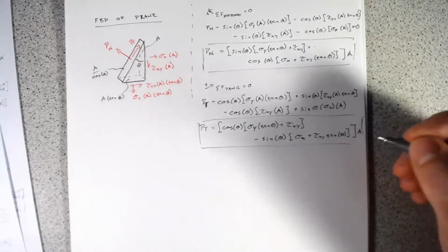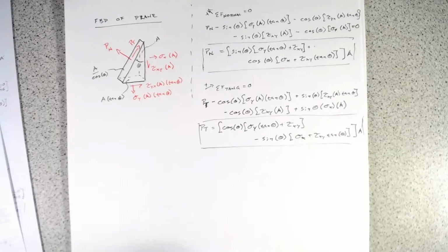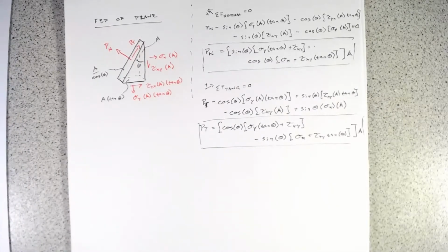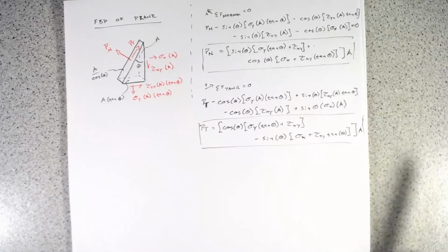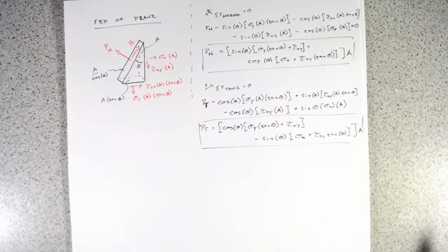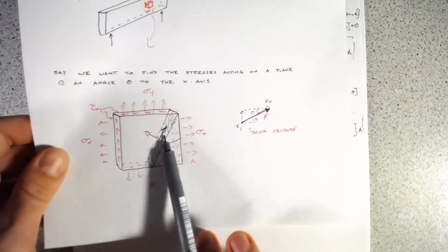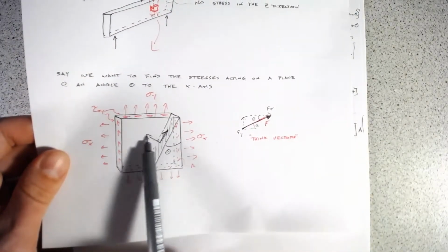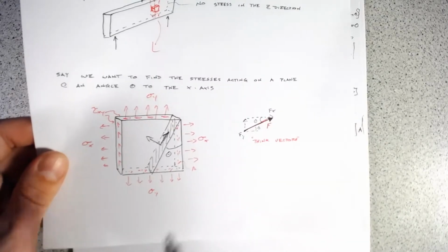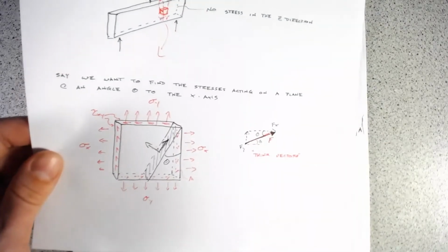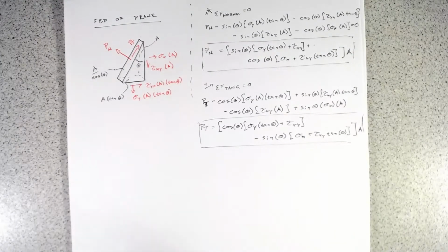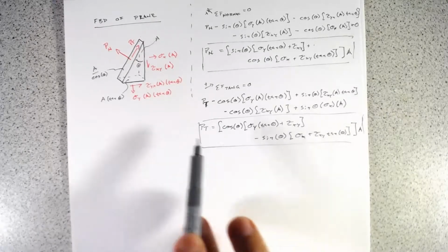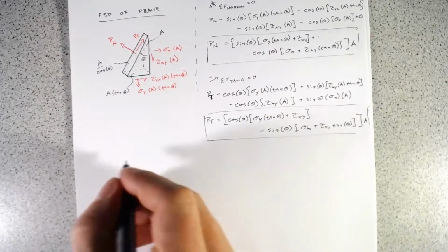forces. And again, and I'll do this throughout the lecture, just try to remind you of what our whole goal is. So the forces is well and good, and that's a lot of trigonometric functions. But remember, what we're looking for are what these stresses are going to be at this inclined angle, because we're looking for what these maximum normal or maximum shear stresses are going to be. So in order to do that, now that we have forces, we need to turn this into a stress.